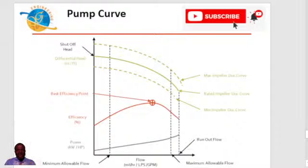This is just like what I explained to you during day 2. That's your differential head, the total head requirement, which is plotted along the vertical axis. Don't forget I mentioned that the total head requirement on the vertical axis is expressed in meters, while your flow or capacity is expressed in cubic meters, liters per second, or gallons per minute, as you can see here.